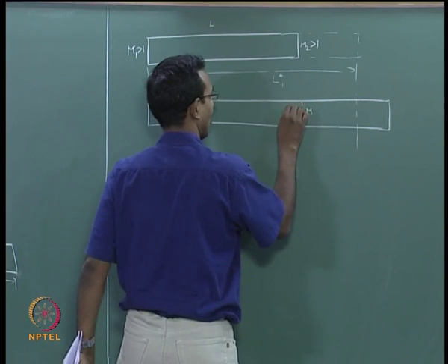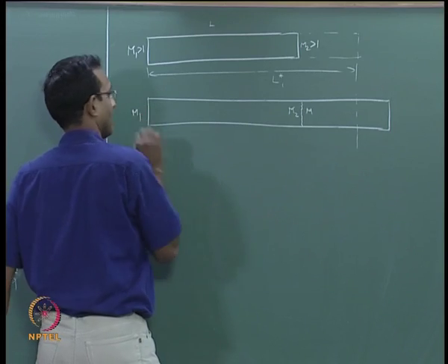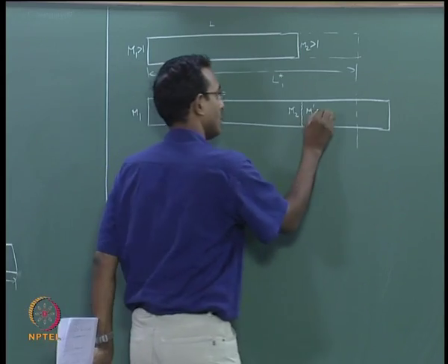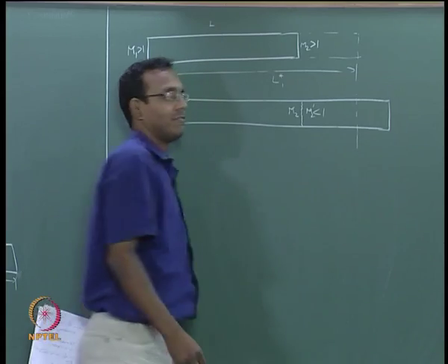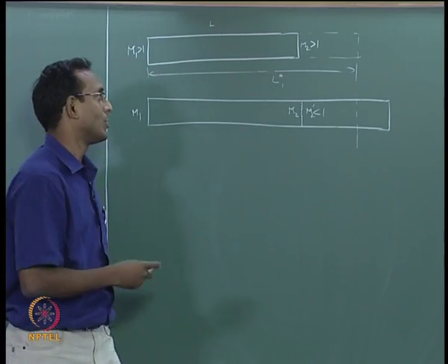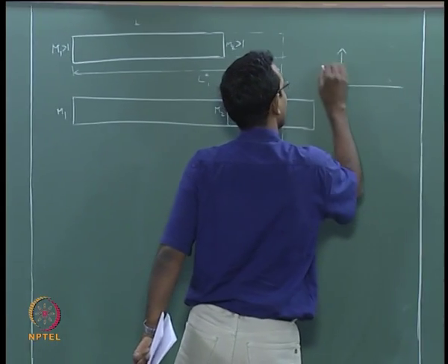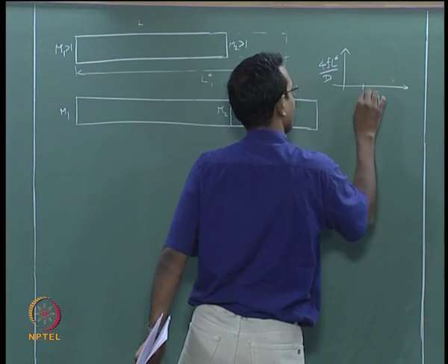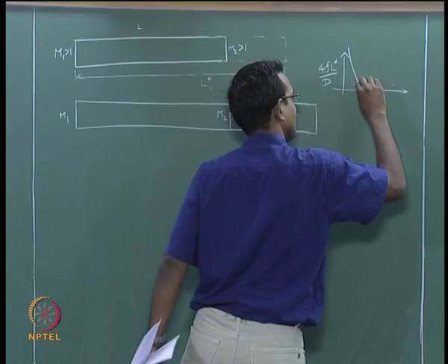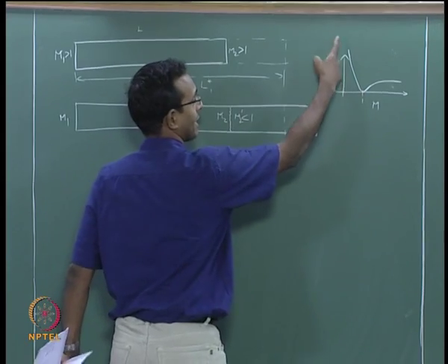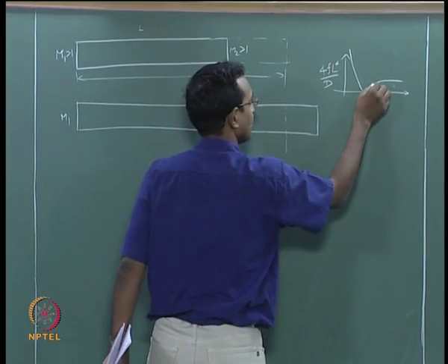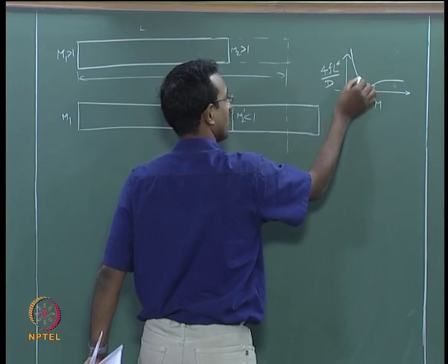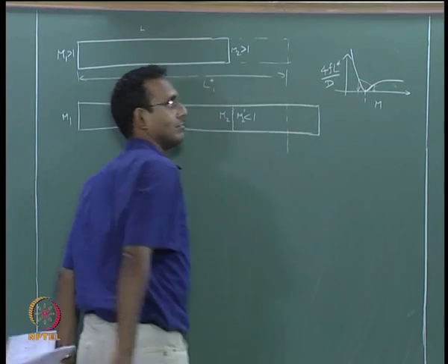Here it is subsonic flow. Now, I will call this M1, M2, M2 prime, just downstream of the shock, immediately downstream of the shock, this is less than 1, and after that it takes the subsonic path. We discussed this on the plot that day, because in the subsonic section for F L star by D versus Mach number, we found that in the subsonic region L star can be much higher. Okay. So, instead of going the supersonic way where the L star is only this length, it takes a subsonic solution where it has higher length. Okay, that is the idea.